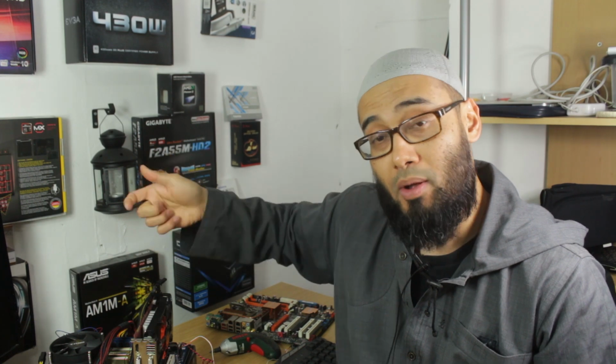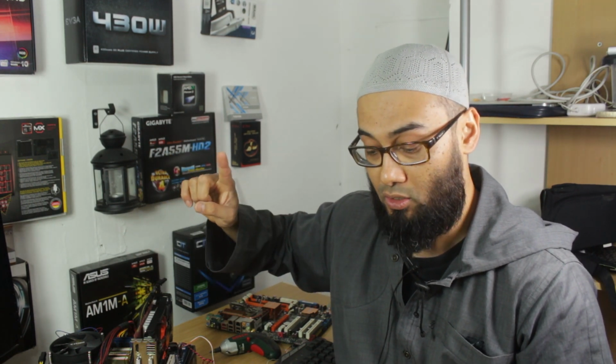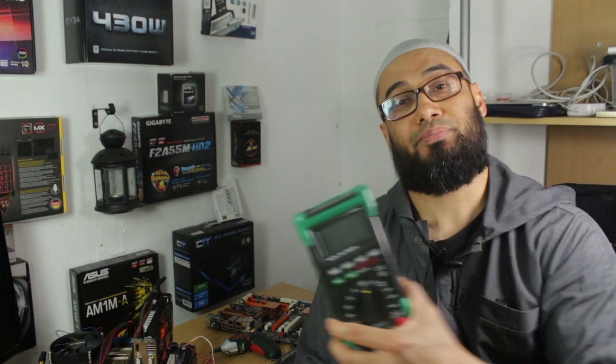Now, before you consider breadboarding the motherboard, there are a couple of things you need to do, some general troubleshooting. Things like the RAM: you can take them out and reseat them, or even swap them with different RAMs. What you can do also is check all your cables and all your plugs. Definitely you should test the power supply and refer back to my video. You can either do the basic test with a clip, but better to do the advanced troubleshooting test with a digital multimeter like this one.